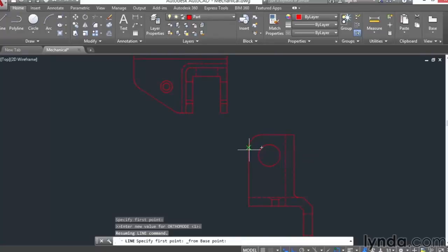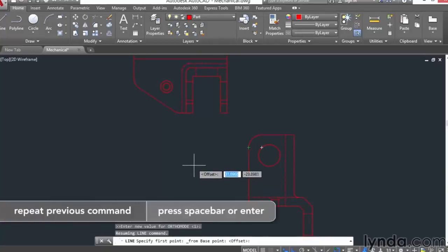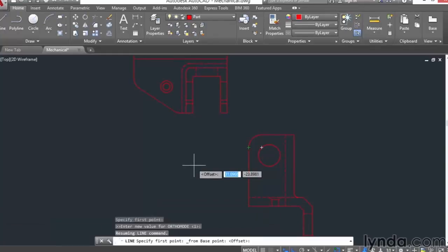And if I move it around some more, we'll see the intersection of the arc and the line. All three of those snaps are coincident, so it doesn't matter which one you click. I'll click here, and now the prompt says offset, and it gives me 2 coordinate values. I want to specify a point that is 10 units to the left horizontally from the point that I clicked. So I can do that using either Cartesian or polar coordinates, whichever you're most comfortable with.